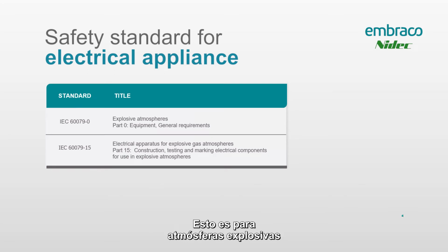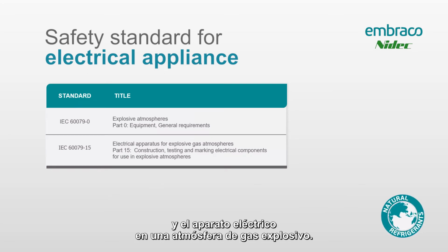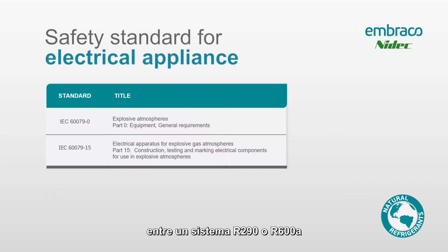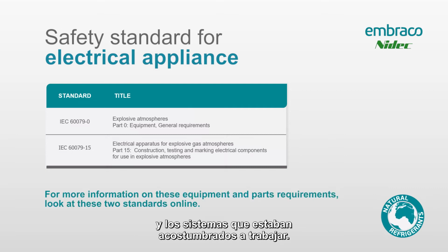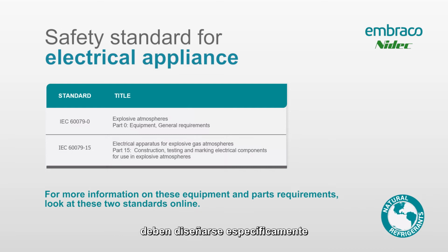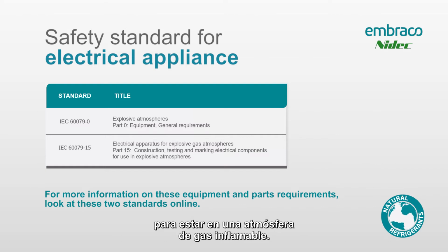So this is for explosive atmospheres and the electrical apparatus in an explosive gas atmosphere. This is where you'll start to see the real changes between an R290 or an R600A system and the systems that we're used to working on out there. What this means is that all of the electrical components inside that system need to be specifically designed to be in a flammable gas atmosphere.